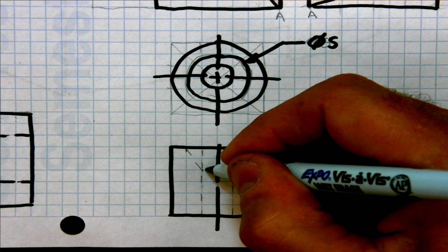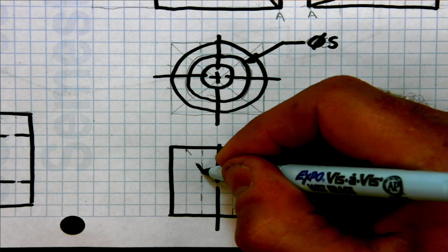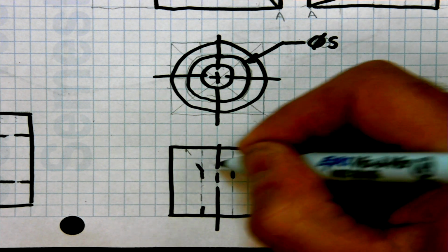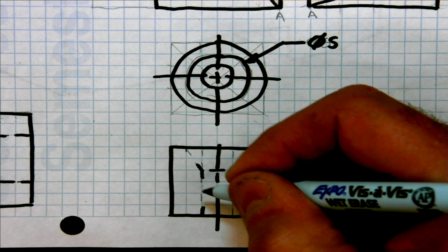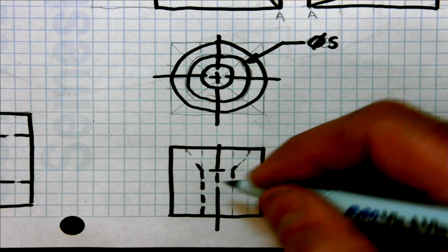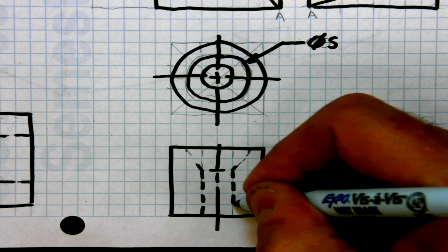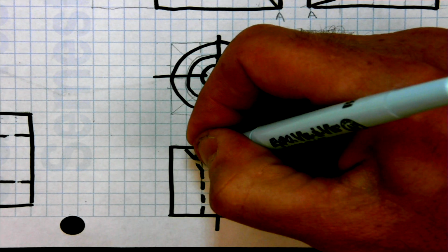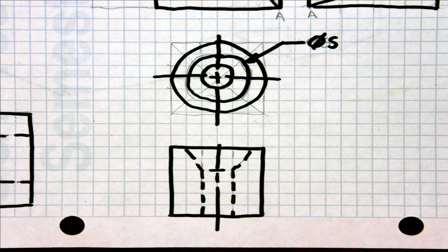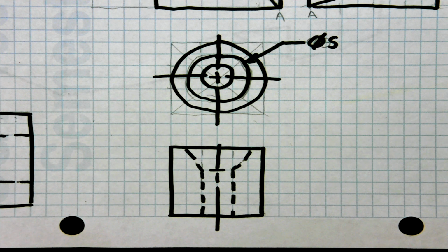We have a line. This is kind of making a Y shape there, but then you have that dashed line that goes across. Dashes, like these dashes, not dots. Make sure they're visible in there. So now there is the countersunk hole in that view. I got a little bit rounded there.